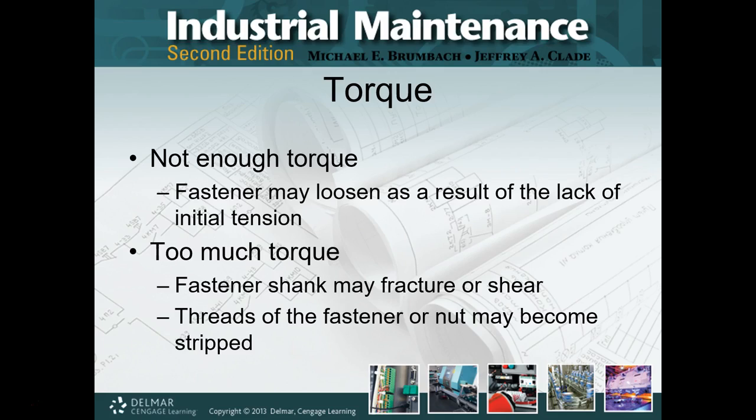So the importance with that is we need to make sure we put in enough torque. If we don't have enough torque, things get loose, and they either shift, like I was talking about before, and they shift and they rub on that fastener, and you can usually tell that when the threads are worn away, or if the fastener has been deformed due to shear.